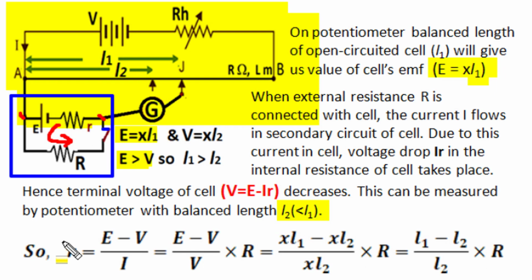And we know for a cell, the voltage across internal resistance is the difference of EMF and terminal voltage when current I is flowing in the cell circuit, and the current I of this tertiary circuit through the internal resistance of the cell is the same as at the time of balance. There is no current in the secondary galvanometer section, and the current of the tertiary circuit is terminal voltage divided by known resistance. EMF corresponds to balance length XL1, terminal voltage corresponds to length XL2, and in a ratio calculation the potential gradient will get cancelled out.